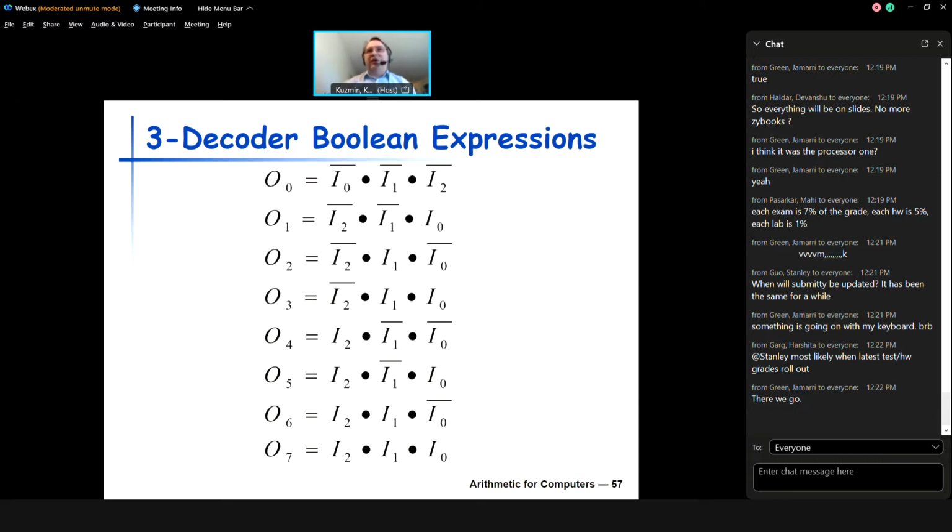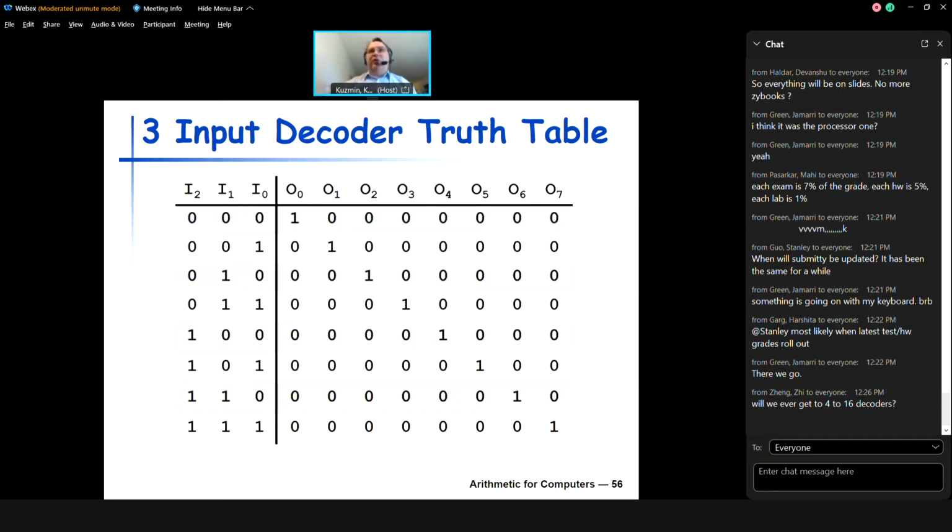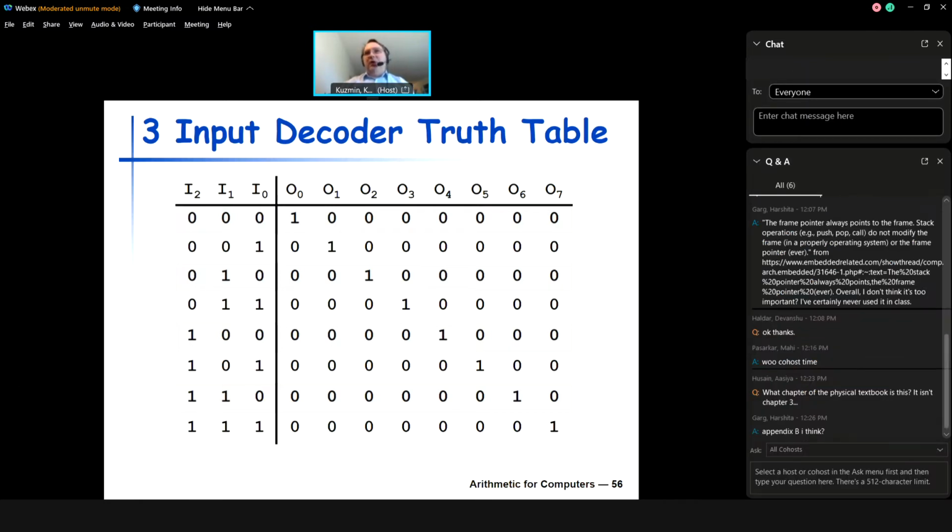are very important. And it turns out that you usually are able to do something like that, maybe with slight modifications. Like with a decoder, you actually need to have a decoder with the enable signal to do that, right? And enable signal is just something that turns off the entire output of the decoder. A regular decoder without enable, you always have one of the outputs asserted, as you can see from this truth table, right? So if we are building higher order decoders using 2 decoders or 3 decoders, that kind of prevents us from actually doing this.